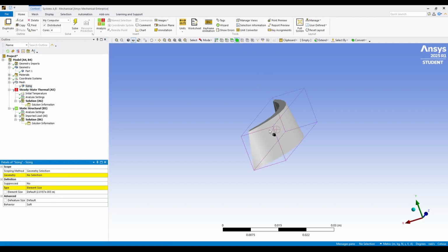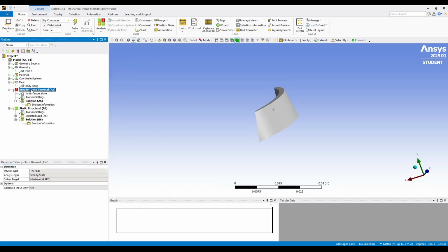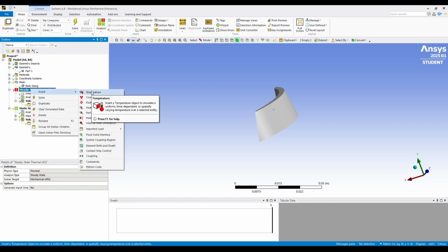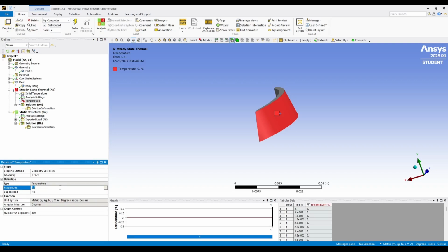To capture the combined effect of mechanical and thermal loads, the temperature results from the steady-state thermal analysis are imported into the static structural module. This coupled structural thermal analysis allows thermal strains to act simultaneously with hydrostatic pressure and self-weight. The resulting stress and deformation patterns represent realistic operating conditions that dams experience throughout their service life.